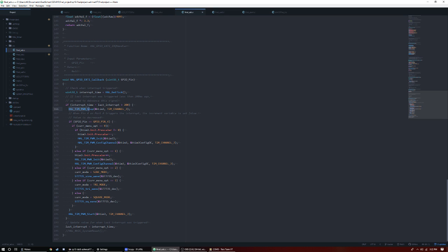The reason I was running into problems with drawing these waves on the LCD with the PWM still going, I think, is that if the system's in the middle of drawing something to the LCD via the SPI and it experiences an interrupt, the LCD enters a bad state, and you have to reboot it. So to mitigate that, I just stopped the PWM and started it again.